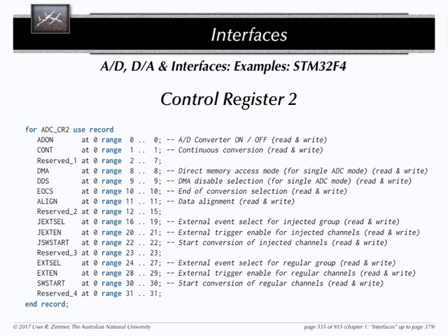The compiler will tell you that you said this is for 3 bits, but the type you have there is actually a 2-bit wide type. That doesn't fit in there. Even if you get that right, you still have the check at the end that the whole record has to have exactly 32 bits. It has to fill exactly a word. So if you mess up one of those, you will again be told off by the compiler that this doesn't go together.